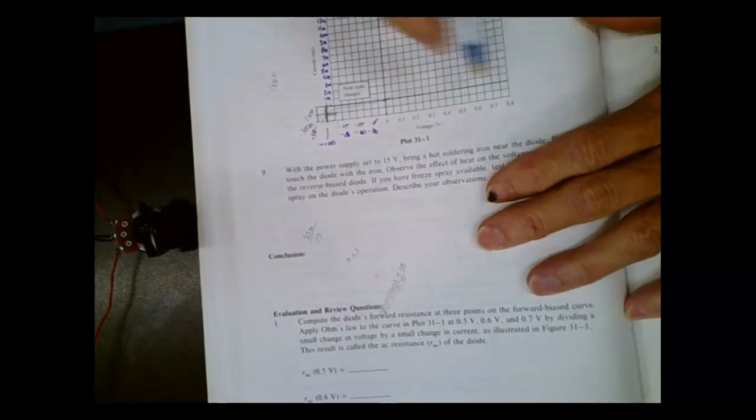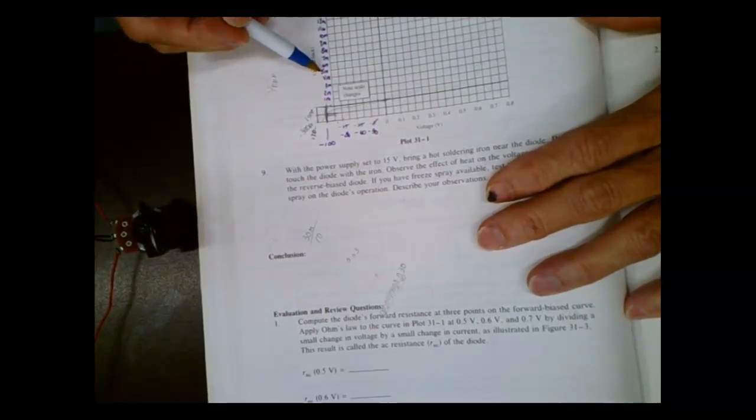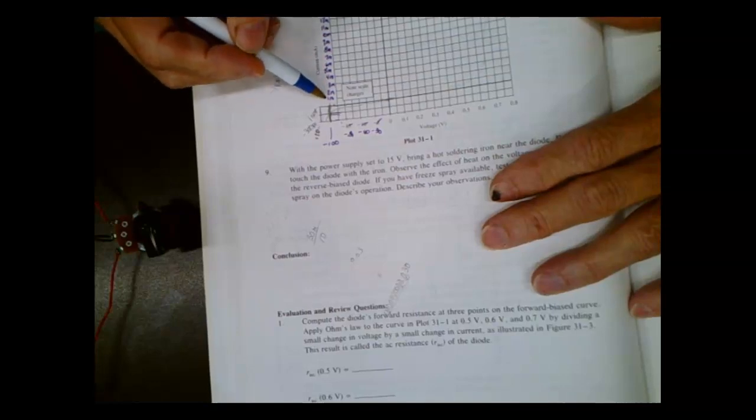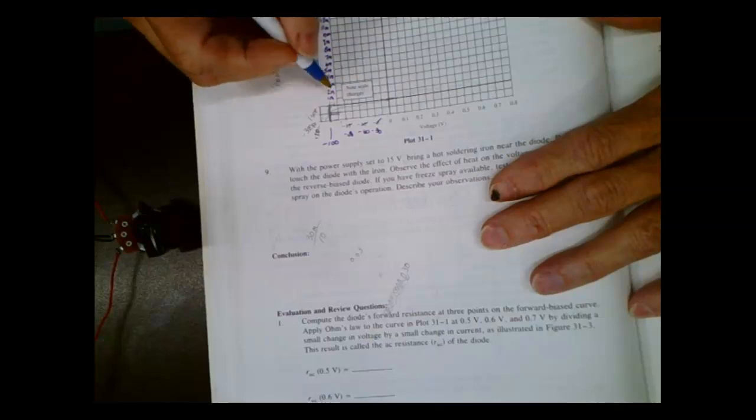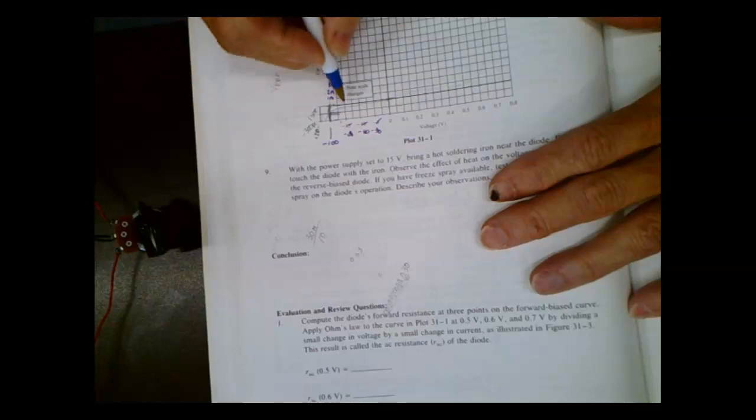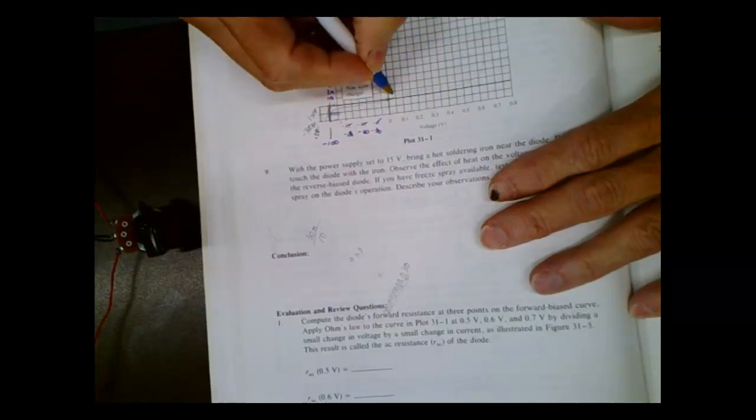So what we're going to do is slowly increase the current. There's 5 milliamps right there. 1 milli, 2 milli, 3 milli, 4 milli, 5 milli, all the way up to 15. This is in milliamps, by the way. Then we're going to come up here and chart this, and we're actually going to see the characteristic curve for the diode. We should see it start conducting around 0.7 of a volt, right? You understand that? Should see it conducting.